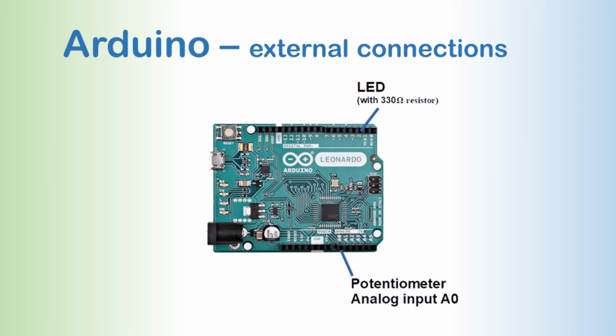I haven't used digital pins 0 or 1 as those are the serial pins on the Arduino, so I'll leave those for future use if I switch to direct connection. Also, for certain Arduino boards, connecting to those can prevent reliable uploads through the USB port, so they're best avoided anyway.